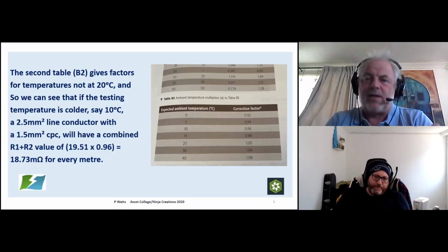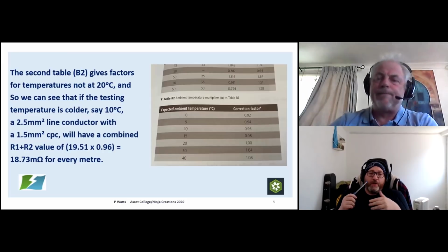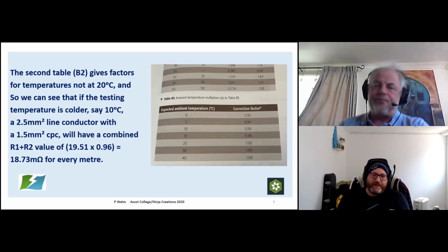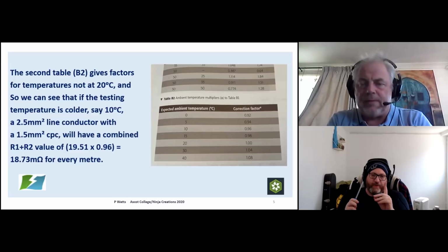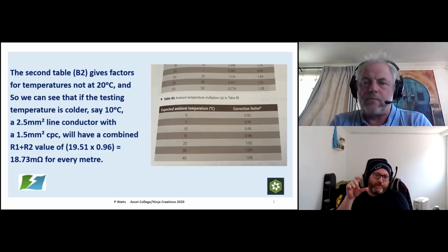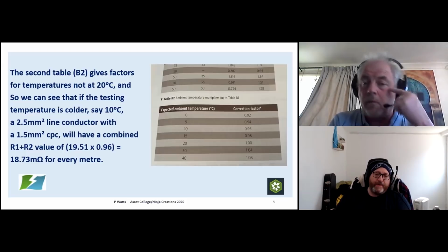Well, and this is the crazy thing. As Paul said here, surely fault currents won't increase that much to cause a serious issue. The theory is that a lowered resistivity would create an increased fault current. And so if we installed a conductor, assuming it to be running at one temperature, but running at a much colder temperature, the science would say there's going to be a point where there is going to be a problem on that cable in a fault condition. But as Phil's just stressed, it's probably going to be quite a significant difference to determine that increased level of fault current.